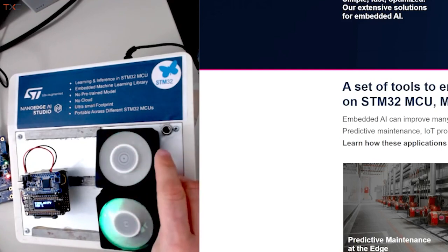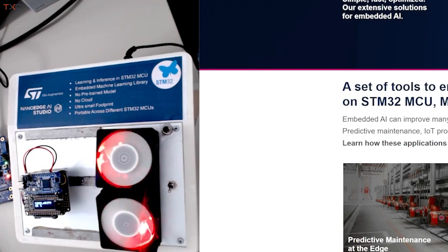So if I switch to this mode, you see the fans are running differently. And so on the screen you can read that the similarity level dropped to 0%, meaning that it is no longer similar to what has been seen by the system during the training phase. And so we trigger an anomaly. We say on the screen there is something abnormal occurring on the machine.